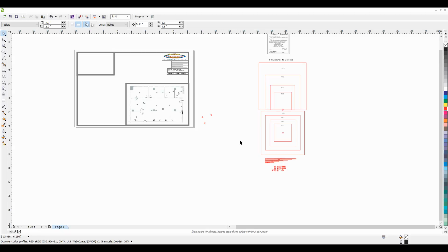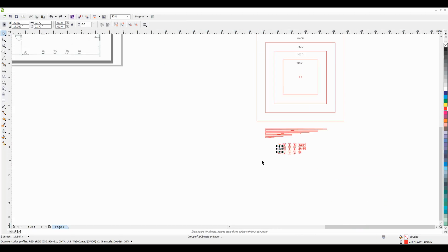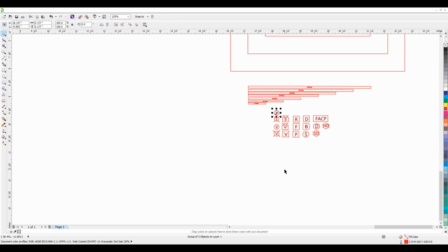You can either do one of two things. You can either drag them out, which is what I like to do, but sometimes it creates a mess if you're using this as the previous drawing, or what you can do is Control D, which is duplicate. The other thing you could do is right click and then duplicate as well. Actually, there's no option for duplicating that way. It's copy and paste effectively, but by pressing Control and D, you will duplicate the object above itself, approximately an inch or however you have it set up to. I believe the default's about an inch or an inch and a half. I'm not sure. It looks like it's half an inch.